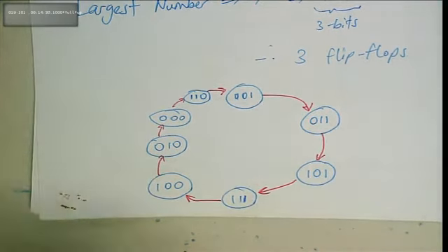Now, the next step is, as per what we did in our lectures last week, Thursday, we convert this into a table. So all we're doing is, we're just playing around with formatting. First it was in decimal format, the state diagram. Now we are building a counter in binary, right? We've converted it to binary so we can reflect on how many flip-flops and all that. So this could be the most significant flip-flop, middle, least significant flip-flop, right? So remember, each flip-flop holds 1 bit, and we need 3 flip-flops. And we've already been told in the question, hey, use a T flip-flop, right? Use a T flip-flop.